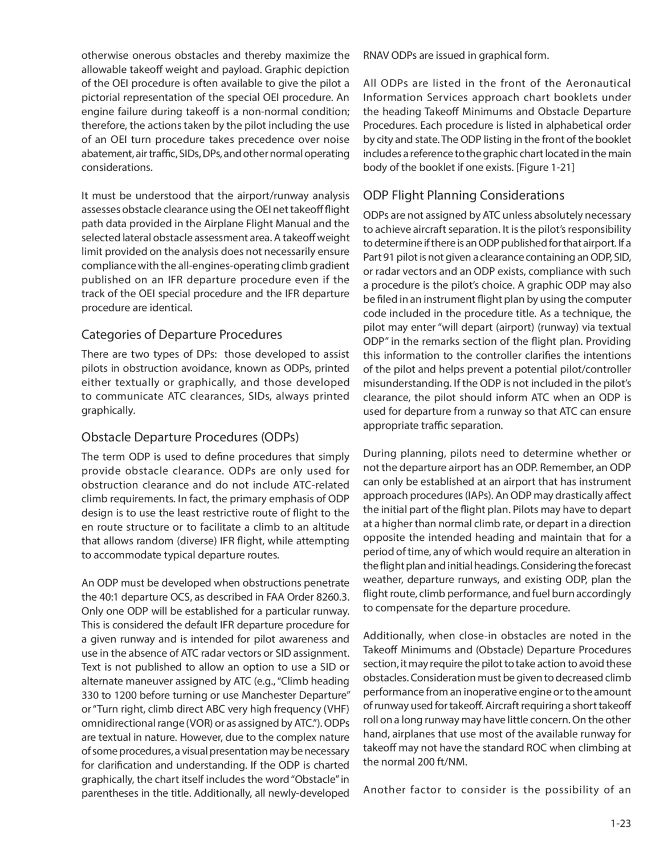During planning, pilots need to determine whether or not the departure airport has an ODP. Remember, an ODP can only be established at an airport that has Instrument Approach Procedures, IAPs. An ODP may drastically affect the initial part of the flight plan. Pilots may have to depart at a higher than normal climb rate, or depart in a direction opposite the intended heading and maintain that for a period of time, any of which would require an alteration in the flight plan